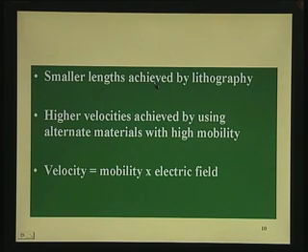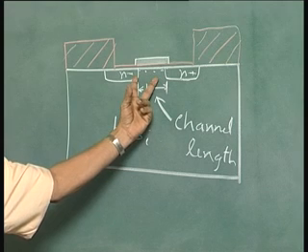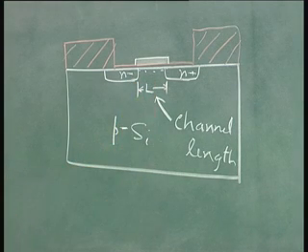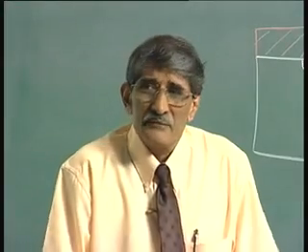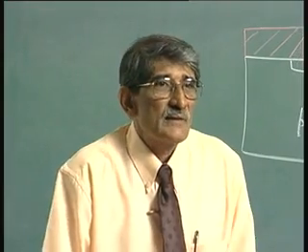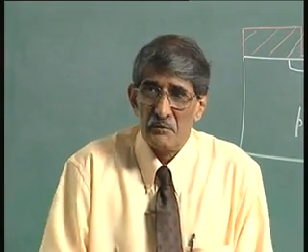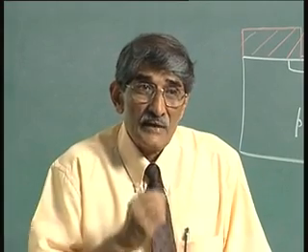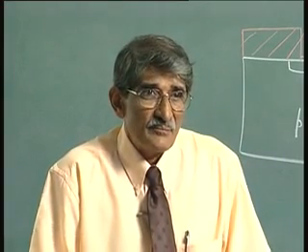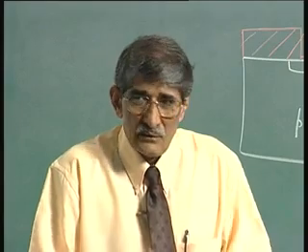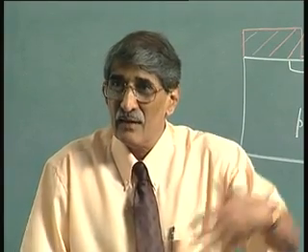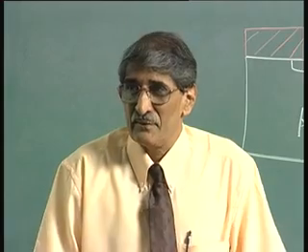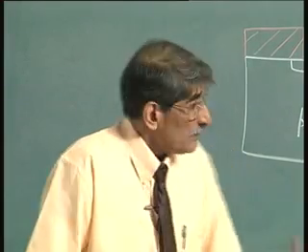What we have is, we can define channel lengths in semiconductor complex, I think about 0.8 microns. So, we are far lagging, because when you go down to smaller and smaller channel length, you need better and better lithography, and the technology is more and more complicated. It gets more and more costly. So, if you can handle this problem with longer channel lengths, still have higher transit times, you are in business. I hope this point is clear.